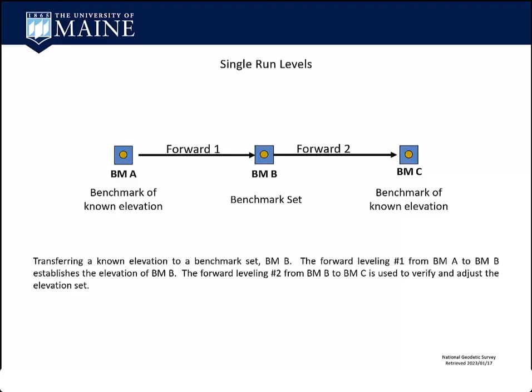You read a lot of rod readings, you wrote them down, and did something creep in there? Did the rod man put the rod down, light up a cigarette, and put the rod back in the wrong spot, and now it's 1/10 higher or 2/10 higher?